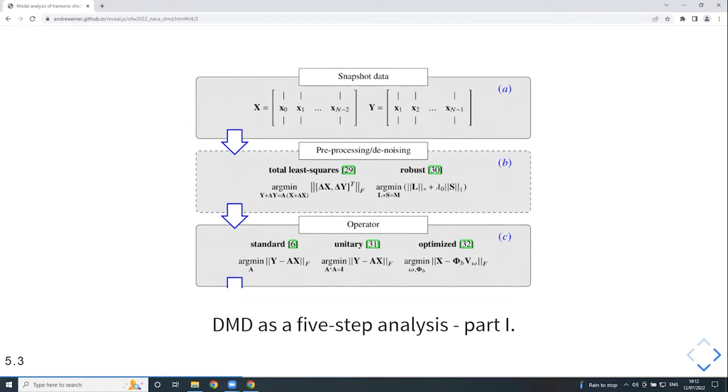All right, here we go with the first 3 categories. The starting point of every DMD and modal decomposition in general are data matrices. In the first data matrix X, we have all but the last snapshot. In the second data matrix, we start from the second snapshot and go to the very last available snapshot. Already here there's some variety that you can use, which is not directly visible in this overview, but you can imagine that inside this very long column vector X, you can put velocity, you can put derived fields, density in case of